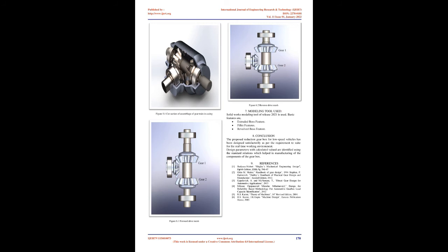C equals 26, C0 equals 13.4. Bearing number equals 6305 ETN9, or 6305-2Z, or 6305 2 RSI.